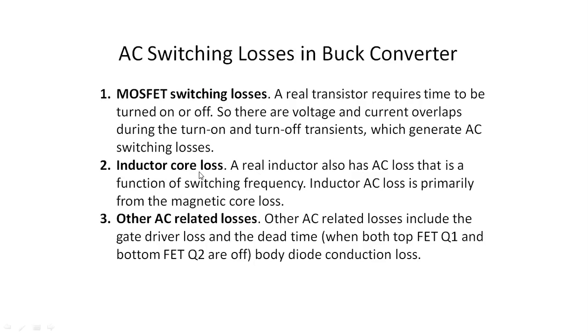Again, there are inductor core losses: a real inductor also has AC loss, which is a function of switching frequency. Other AC related losses include gate driver loss and body diode conduction loss. So there are switching losses, inductor losses, and losses from conduction in the transistor, diode, and inductor.